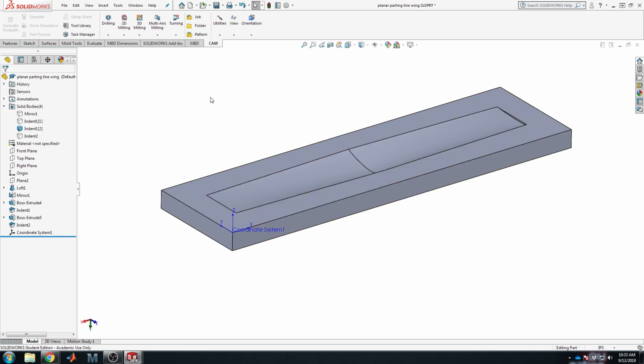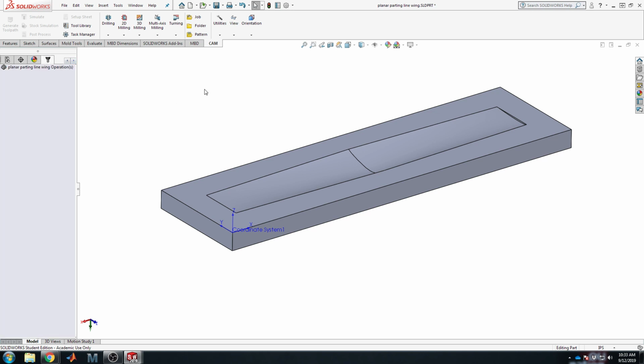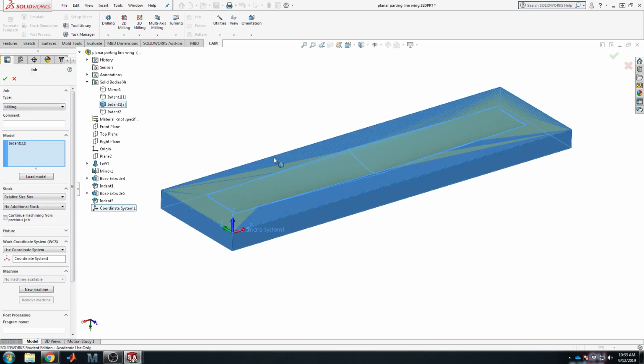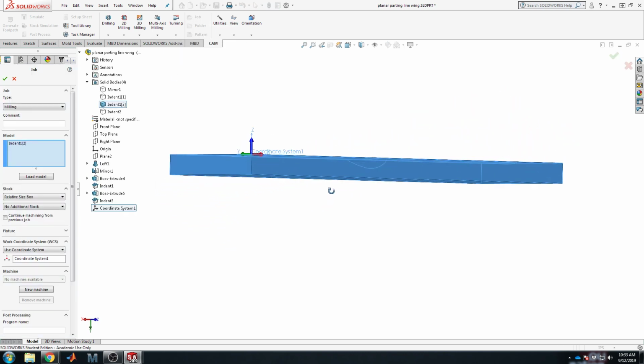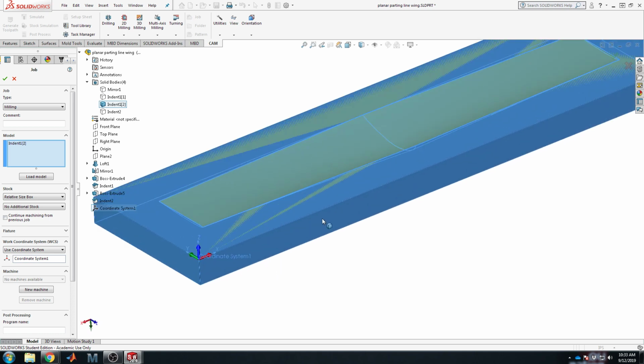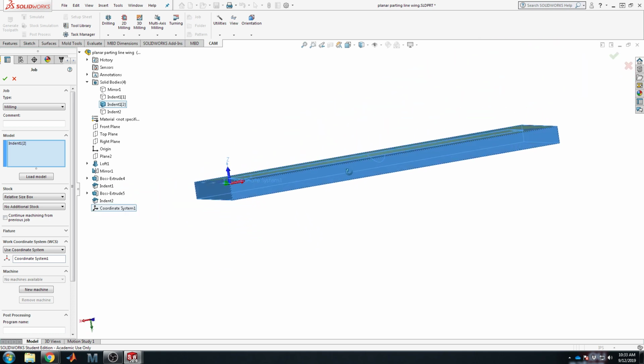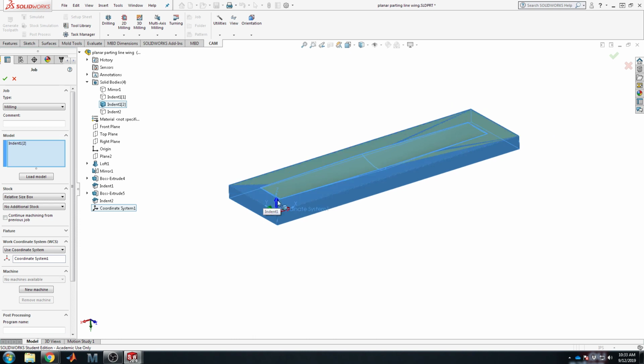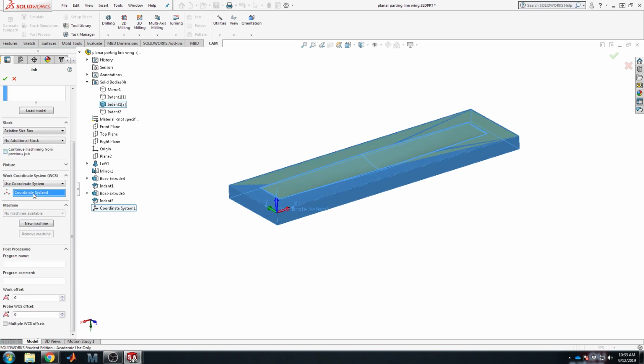So this is where we're at. We have the coordinate system. Let's go ahead and go over to the milling tab, which right now we see we just have nothing. We've made no parts. We've made nothing. So start with the job box. That's where we start things, and it automatically sizes our material stock. It knows how big your part is, and thankfully it can contain all of that solid within one big prismatic chunk of material. So thankfully that's no big deal.